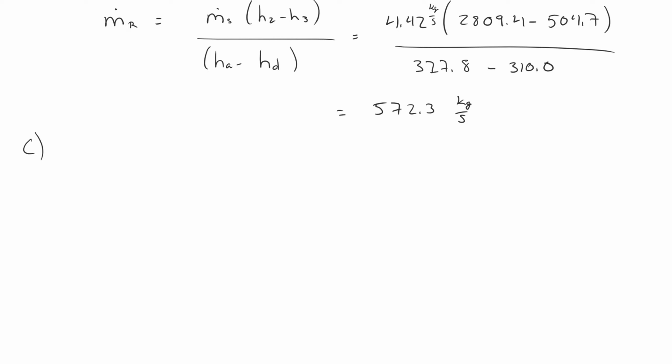I've got W dot cycle over Q dot N. And so I only have to take into account the heat entering my system. So the heat transfer that's happening between the two cycles is within the system, so I'm not concerned about that for the sake of thermal efficiency.